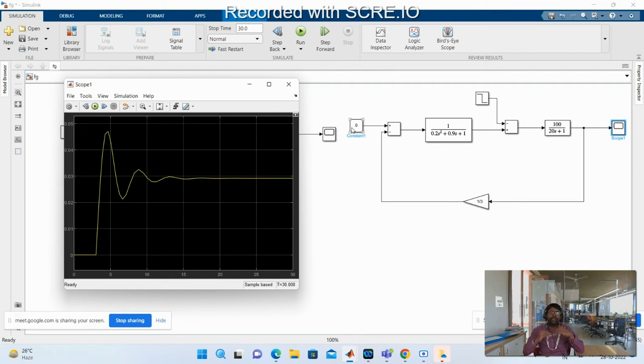Because when the load increases, the frequency decreases. Accordingly, you have to open your steam valve. Then only will the frequency go up again and reach the nominal value. But we are not controlling the steam valve position. We are not changing the speed changer position. We are keeping the speed changer fixed by keeping delta PC equal to 0. Because of this reason, in both cases, you have some frequency deviation.